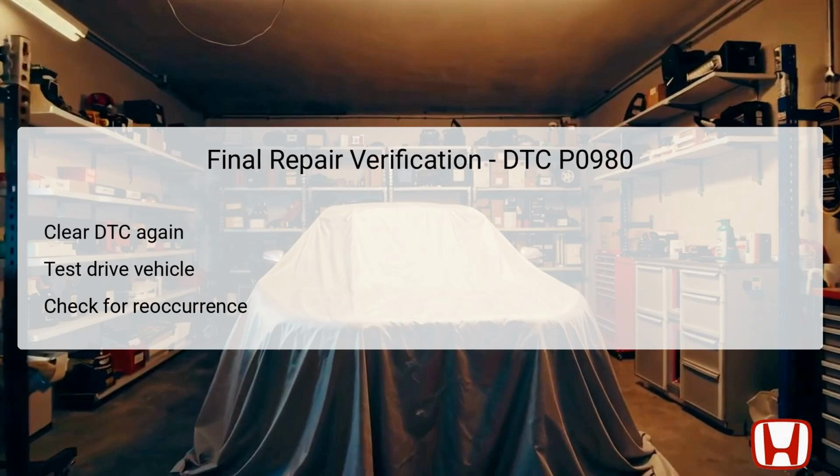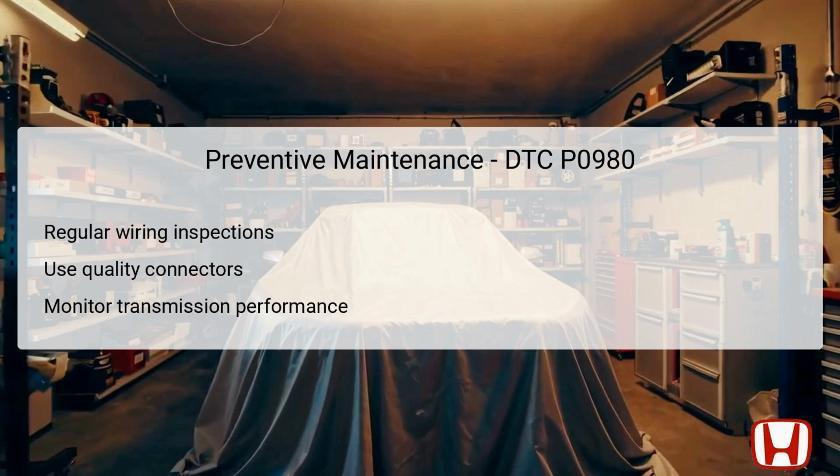The technician should be on the lookout for any reoccurrence of DTC P0980 or new codes that might emerge during this phase. The driving conditions should closely mimic those that presented the original symptoms for accurate results. Conducting this final verification step is crucial to ensure reliability and functionality of the vehicle before returning it to the customer. To prevent future occurrences of DTC P0980, regular and thorough inspections of the vehicle's wiring and connectors are paramount.